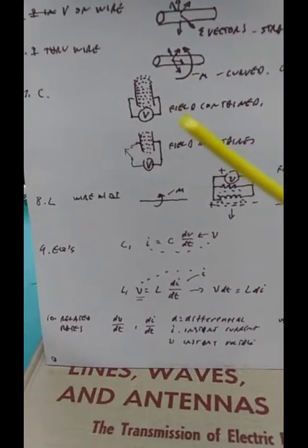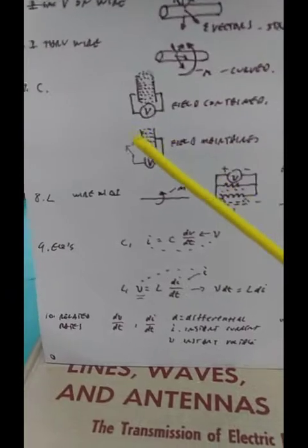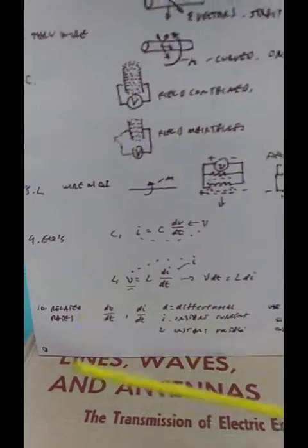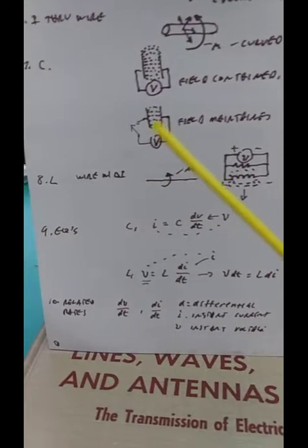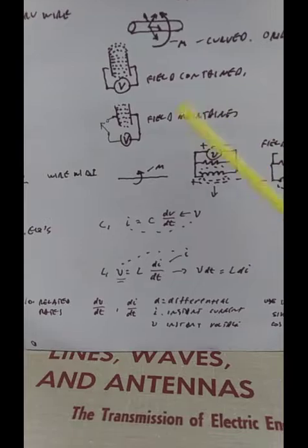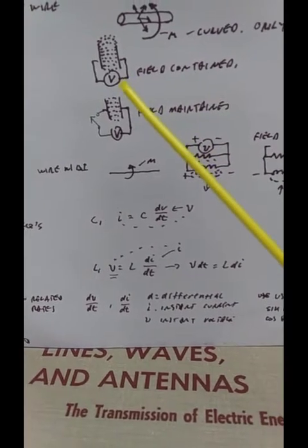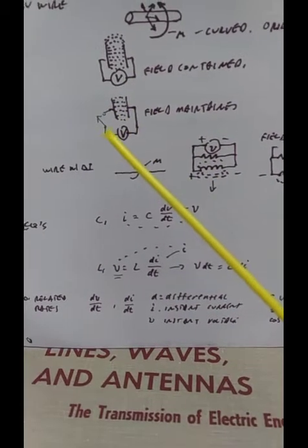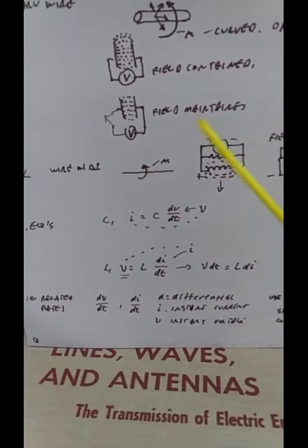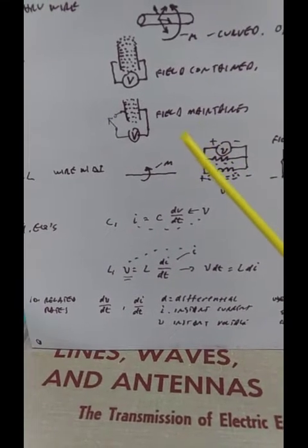It's a terrible early mistake to say that current goes through a capacitor. It looks that way, but it doesn't. That's the electrical field. With the supply open, the field is maintained. Very important, because an inductor doesn't do that.